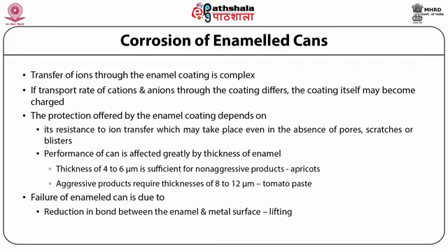Thus, good adhesion is required to prevent anodic reactions, to counteract forces developed under the coating due to physical or chemical factors, and to ensure an aesthetic appearance. Loss of adhesion may begin prior to corrosion due to stresses during fabrication or during processing. But typically, detachment of the enamel coating is a result of breakdown taking place through or under the coating, or under the film corrosion spreading from exposed metal.